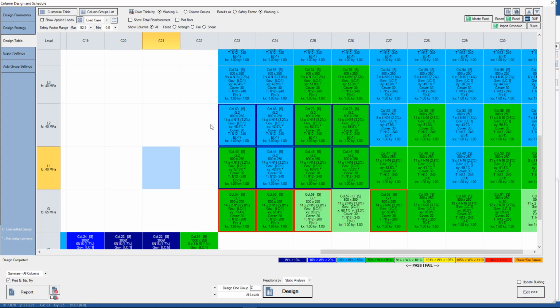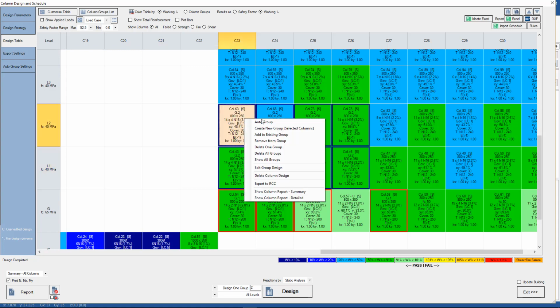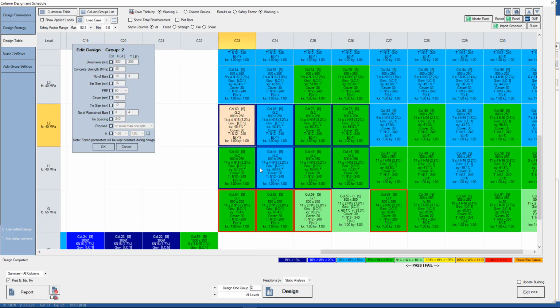And we see the design results on screen. When a column is in a group, we see the group subscript, which we can of course switch off when we export. Now the design values that we see on screen are just the bare minimum calculated by RCB. Similar to individual columns, we can edit the group design by selecting the values, and then we can modify them like so.